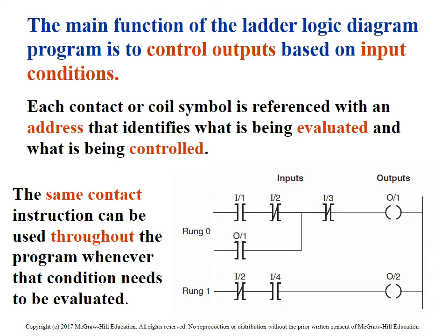So here we are, looking at some more ladder programs. We're looking at outputs and their relation to what the inputs are doing. Here, these series of inputs either have to be on or off to operate correctly, to get this output to turn on.